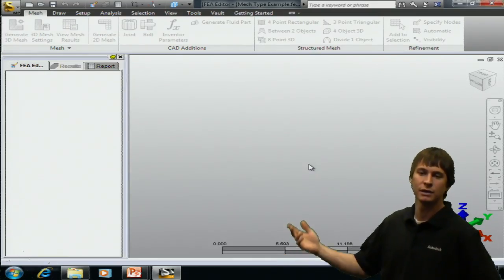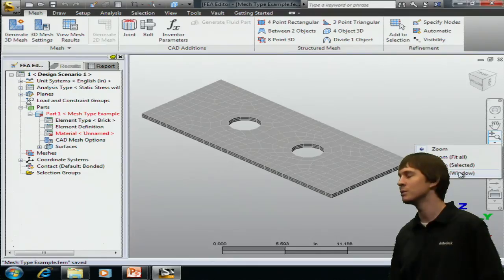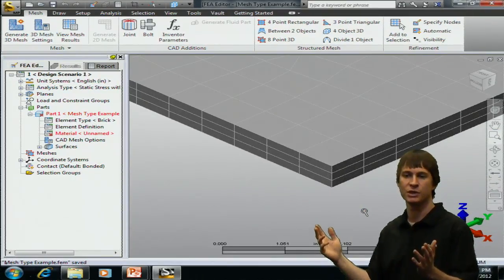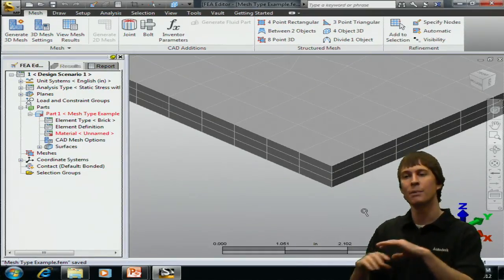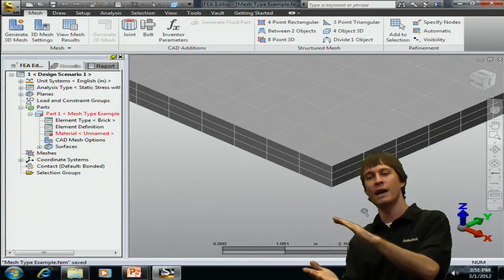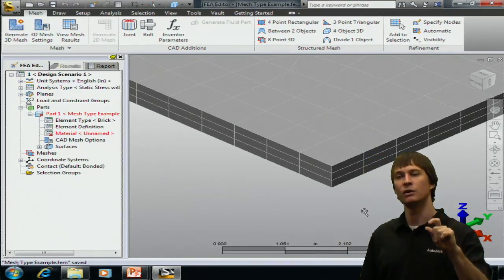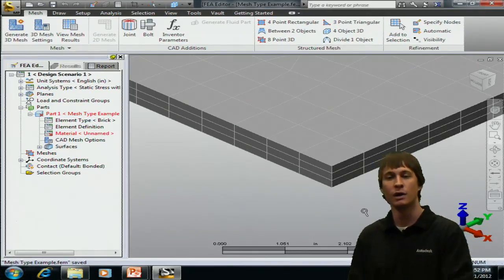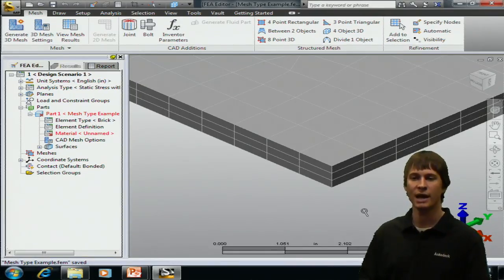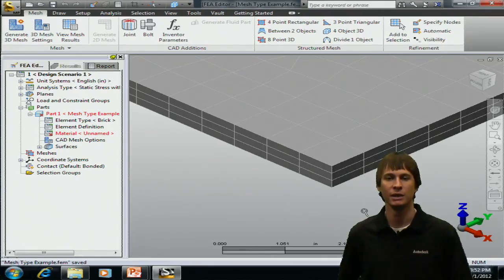Again, you're going to see a very nice surface mesh, but this time, if we zoom in, you're going to be able to see that we have 3 elements through the thickness. So what's this mesher doing? Basically, putting a mesh on a collapsed part and then just expanding that out into 3 layers. So we have the exact same mesh on all of those elements the whole way through. So again, this is best used for very thin parts when you want to have multiple layers through it to get accurate answers with your solid elements.